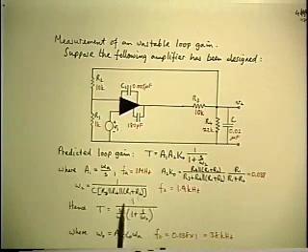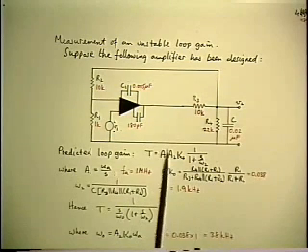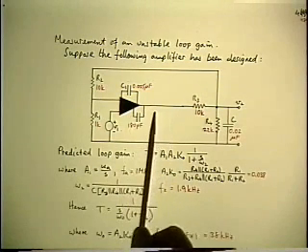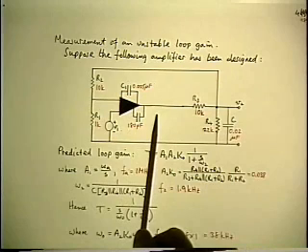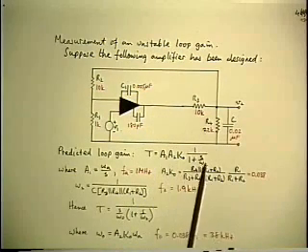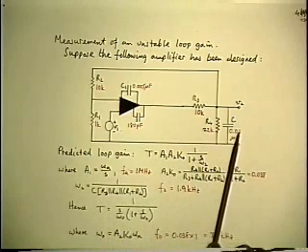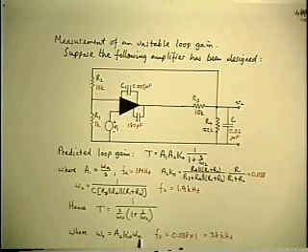So the analysis is the same. Remember, just to review how we did it, we chose an injection point at the output of the op-amp, did series voltage injection, split the loop gain into 3 factors, calculate them separately using the extra element theorem to restore the capacitor after leaving it out at first.